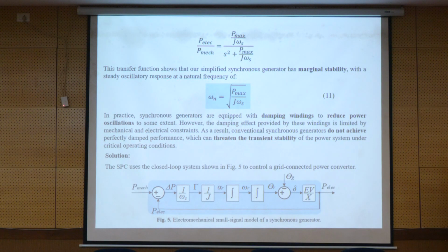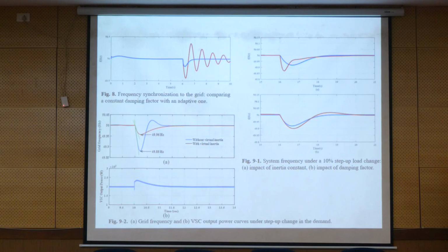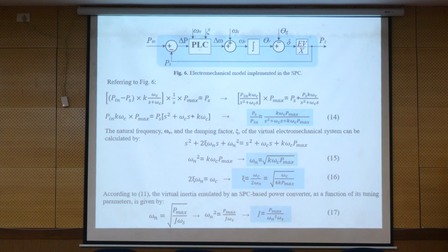When you analyze the stability of the system, you should consider that if we pass that border, the system will be unstable. So when calculating the value of J, you should consider what the natural frequency is, and then you calculate the value of the inertia we need to keep the grid stable.